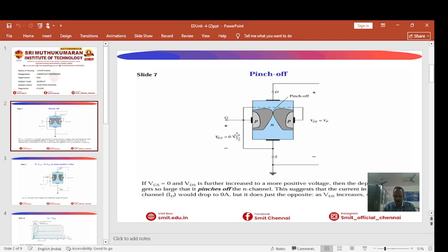The construction of the JFET mainly depends on the channel. Here we are depicting the N channel JFET. The main body is made of N-type material. On both sides of the channel are P regions. The P regions are connected together to form the gate terminal. The two ends of the N channel become source and drain. As I already told you, both are interchangeable.